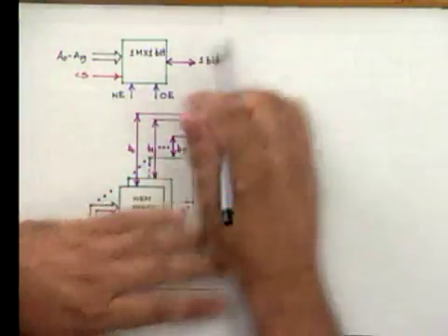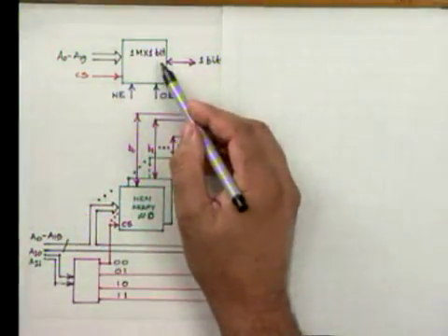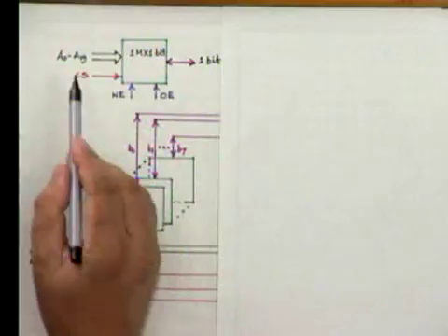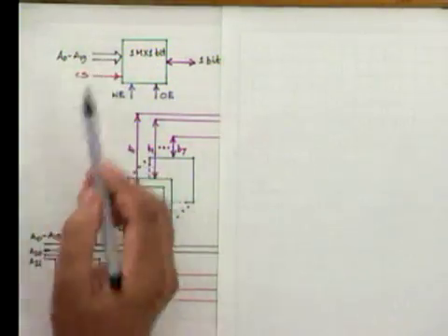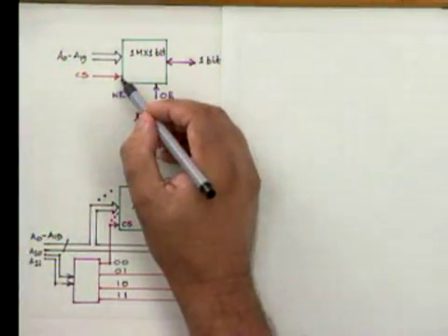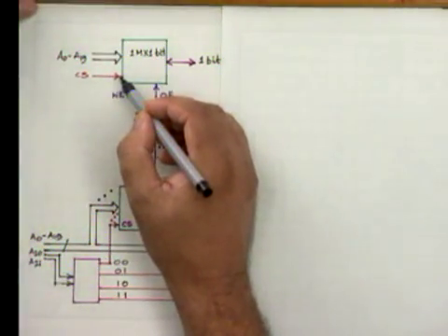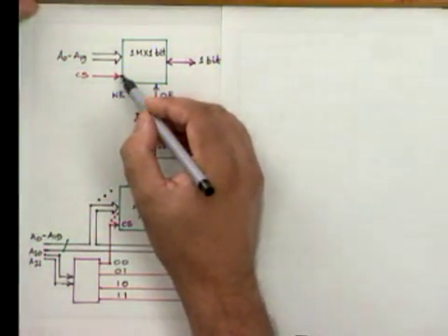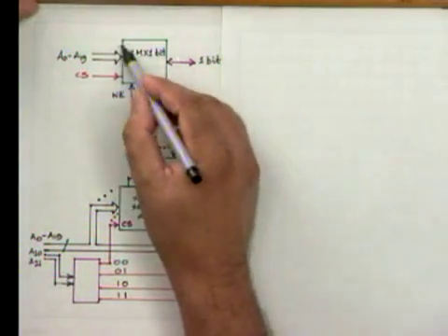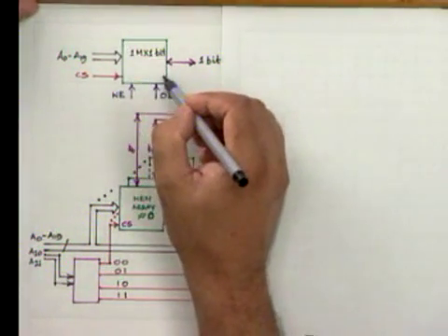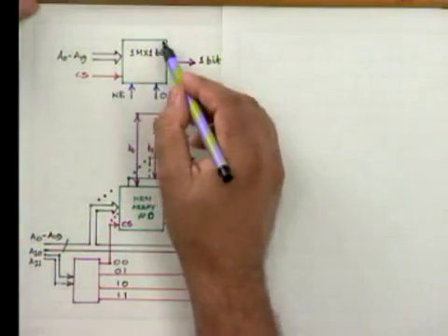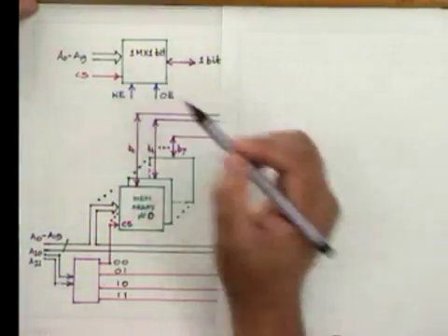This is the chip that we are talking of. We have A0 to A19 address lines. There is a particular input we call chip select input. If this chip select is active, only then is this particular chip selected. Otherwise, the entire chip is inactive.